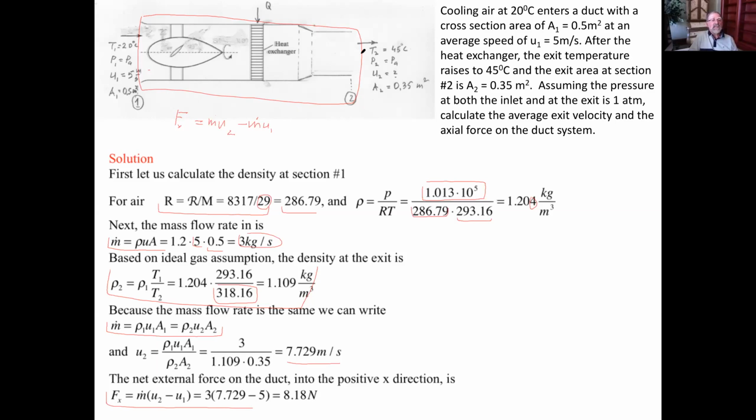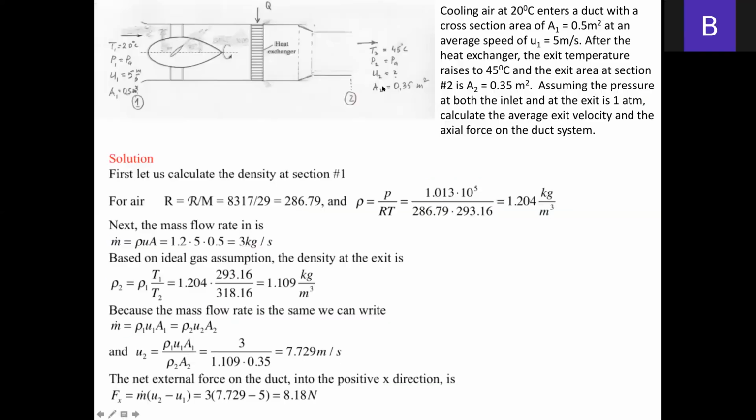So this is a more complicated problem, because I mentioned before that one way to accumulate flow is by changing the density. Now I'm giving you a problem with a change in density, and I'm telling you there is no accumulation. Accumulation would mean that flow stays in, and therefore the pressure will go up. But we stated that the pressure is the same. So I'm okay in my assumption. Am I convincing you or not? Yeah, that makes sense. Thank you.